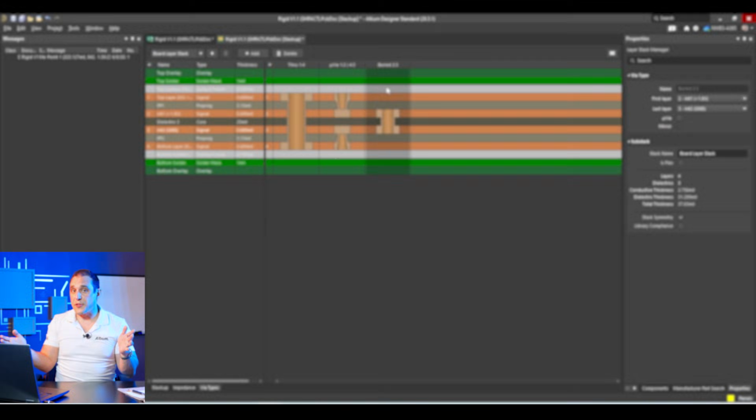And if you're going to be picking your own materials to appear in this stack up, you need to make sure that the dielectric that you use on those outer layers is compatible with laser drilling. So if you're ever looking through materials data sheets, you will see different types of materials that are often marketed for example, high density designs. And oftentimes they will just state whether or not they are compatible with laser drilling right there in the data sheet.